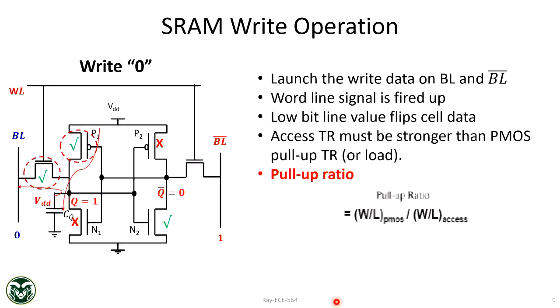Yeah, these are good questions. Any question? If you ask questions, it also gives me time to explain a little bit more. Okay, so that's one important thing. Typically, you design the pull-up ratio around 1.5. You keep margin, right? You don't want to keep it on the edge where NMOS and PMOS are equally strong. You want to take advantage of the mobilities, and also keep some margin.